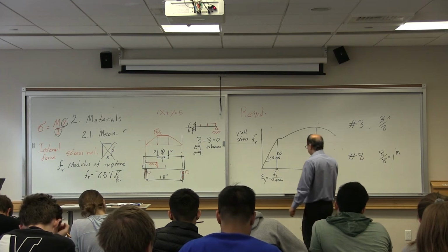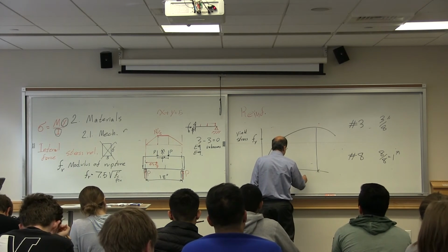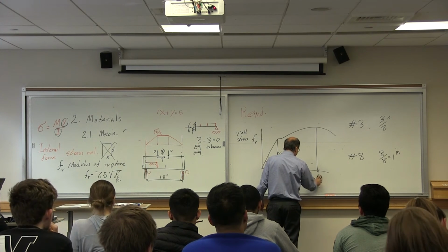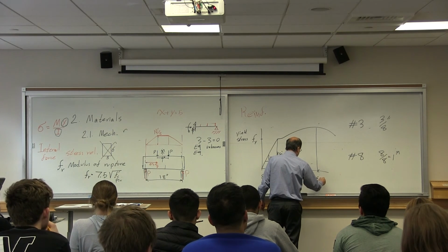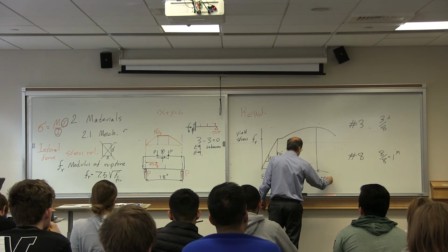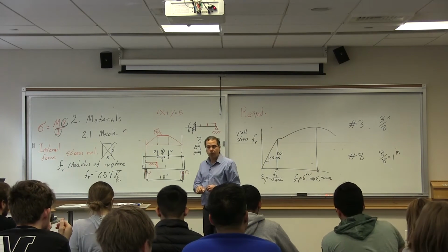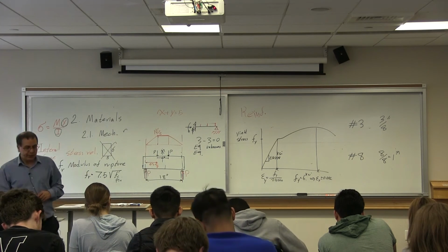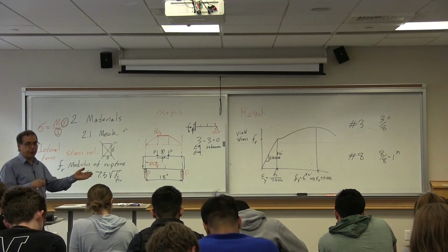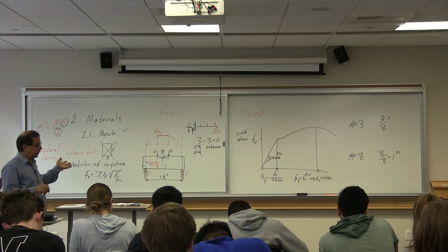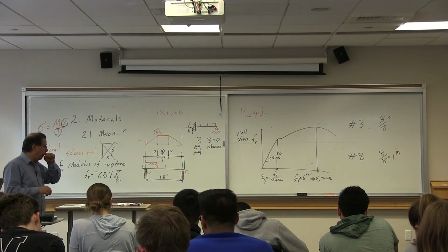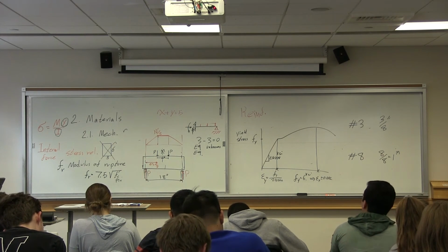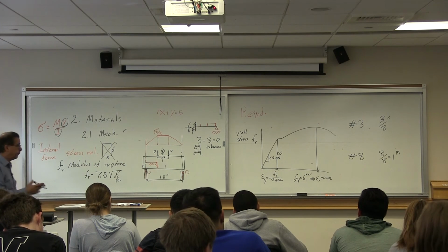If Fy is 60 ksi, epsilon yield is approximately 0.002. It's interesting that this number happened to be equal to the strain at which concrete has maximum strength. Just happened to be.